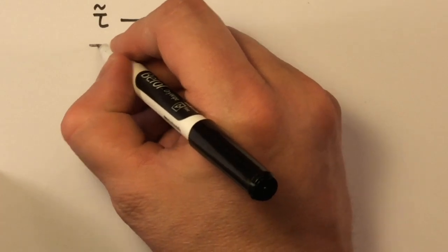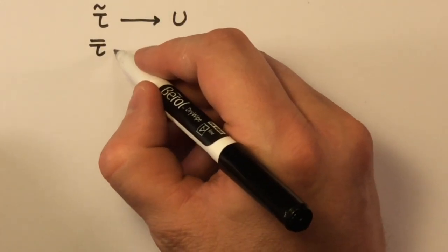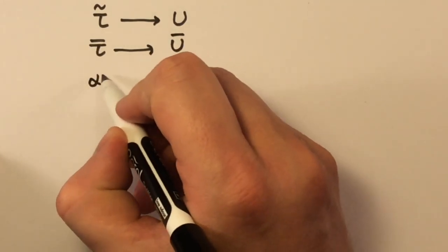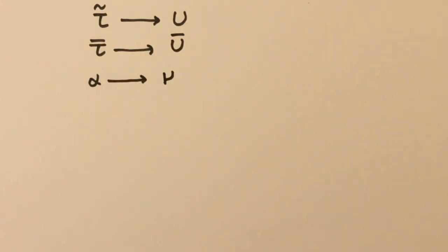So we are not looking at finding the temperature in that case, we're looking at finding the velocity profile. So instead of tau bar, the maximum temperature of the oscillation of the wall, we have a u bar. And instead of alpha, the thermal diffusivity, we have nu, which is the kinematic viscosity. And everything else is equivalent.